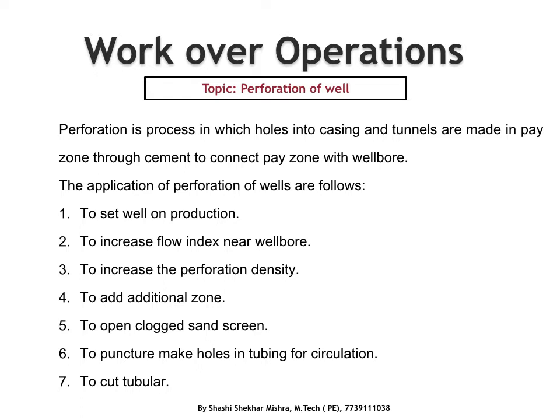Then comes, suppose we are producing from zone A and we want to add another zone in the same completion. Then we do the perforation to add the additional zone, and this can be achieved by doing the perforation in the additional zone, or we do the perforation in the zone transfer.